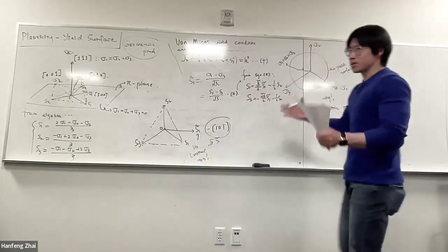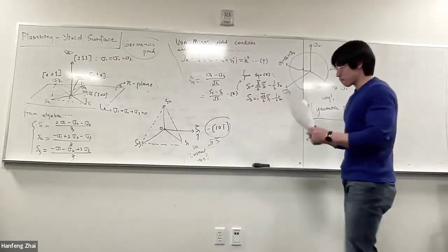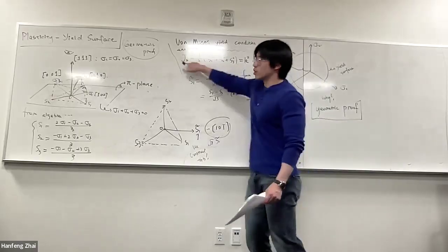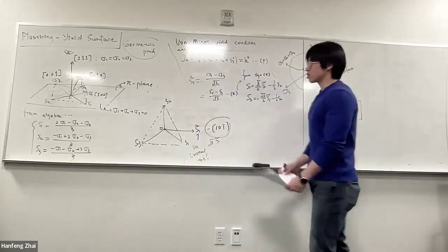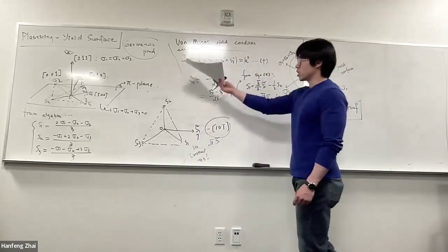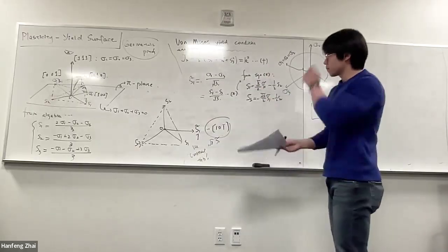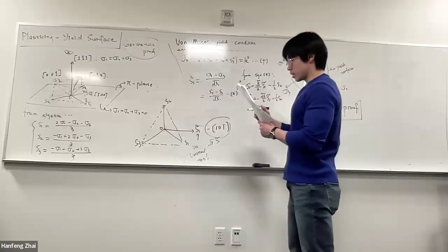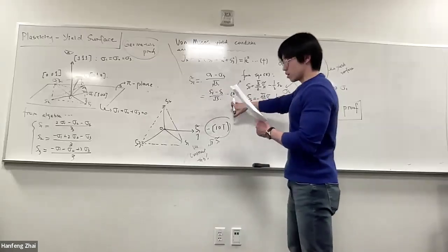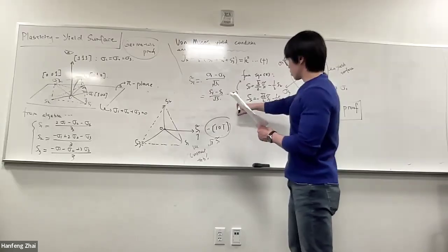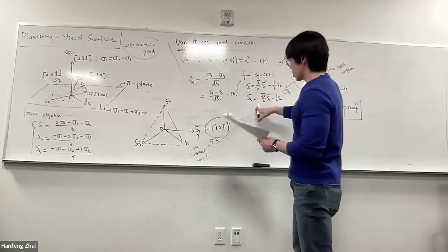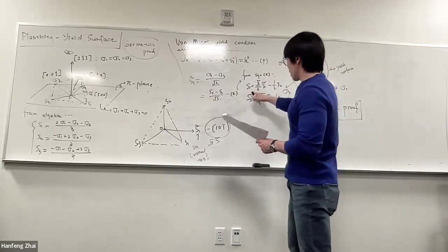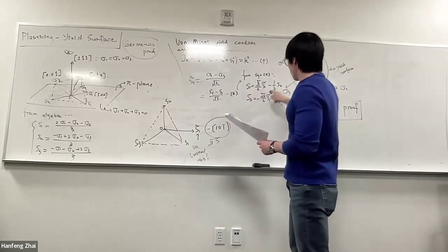All right, so we're still in the middle of algebra. Recall this is the definition of the von Mises stress criteria, which is J2 equals K squared. So now we're gonna substitute equation star and the equations that we derived from equation star, because we already know the correlation between S1 and S1 tilde, or S2 and S1 tilde, S3 and S1 tilde.